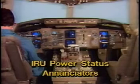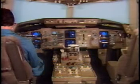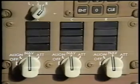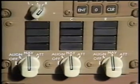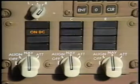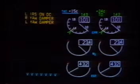Annunciators on the ERMP and equivalent messages on the ICAS reflect the power source in use for each IRU. Loss of an IRU's AC power source causes the associated ERMP on-DC annunciator to go on, and an on-DC ICAS message is displayed.